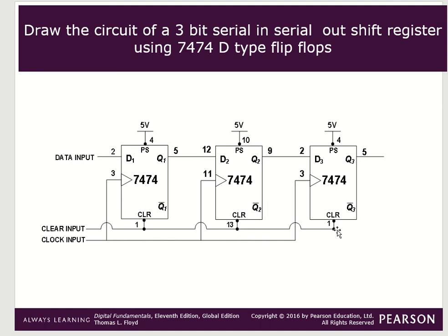Okay, and what is the arrangement of this one? See, this is the input data and this is the output. The first output is connected to the second input, the second output is connected to the third input, and the third output is leaving. So this is the arrangement of the shift register, and preset should be high.